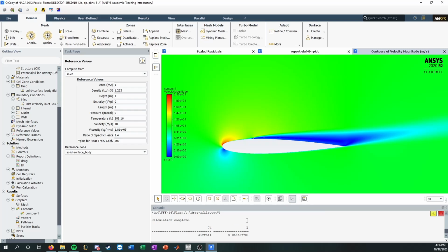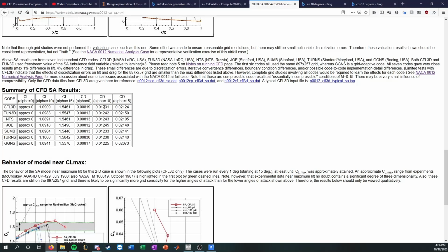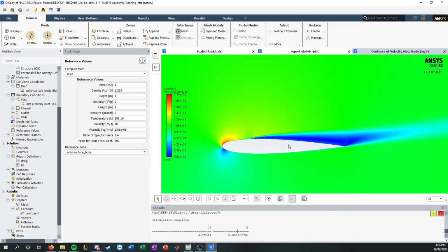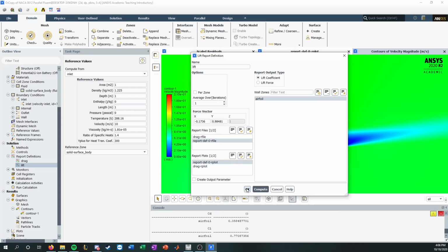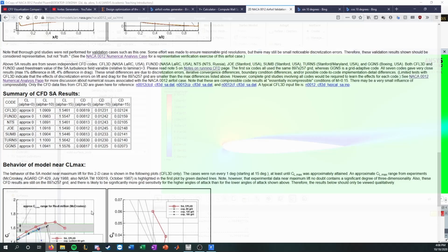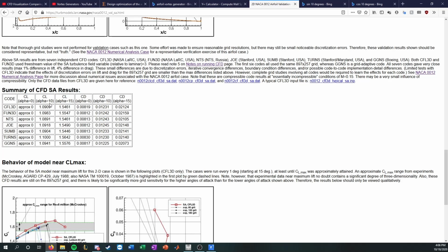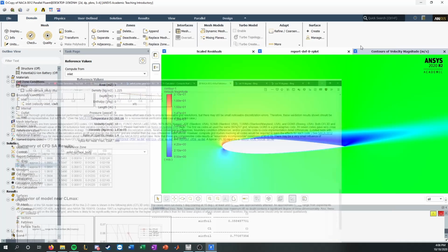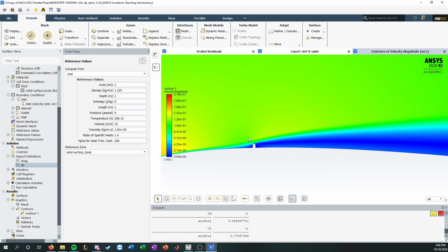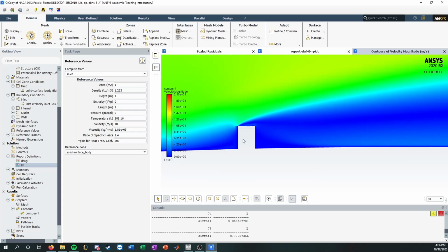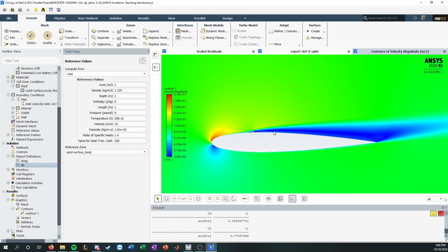In addition, you see the drag is huge, 0.058. We would expect a 10 degrees angle of attack to be 0.01. So that's a failure. And the lift is, yeah, that's not great. At 10 degrees angle of attack, they would expect it to be about 1, but it doesn't match up. So the point being that CFD is not able to capture in steady state any 2D vortex generator. So this is with an extrusion.